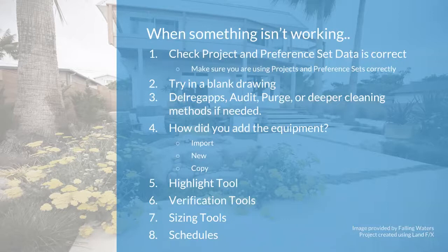If you're not familiar with that process, we have that documented. Make sure that you have one project per drawing or per design, and that you're not using that project over and over on different sets of designs, because once you start doing that, that is where things start going awry. That's where your error accessing equipment data comes into play, because maybe you deleted a head. So just making sure that you have that mentality set up properly will definitely alleviate some of that.